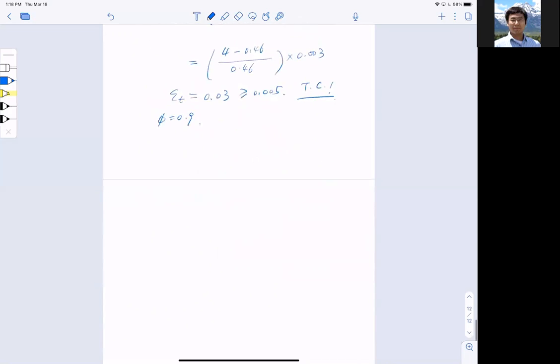Now, finally, remember the process. My nominal flexure strength Mn would equal As Fy multiplied by (d minus a/2). You plug the numbers in. I'm just going to save this step. It is equal to 5.1 kip-foot per foot. I cannot emphasize this enough: the unit is kip-foot per foot.